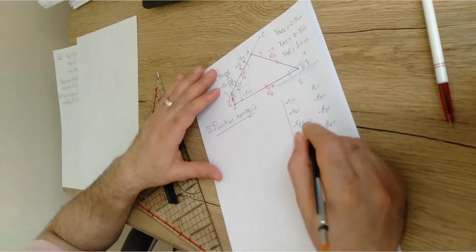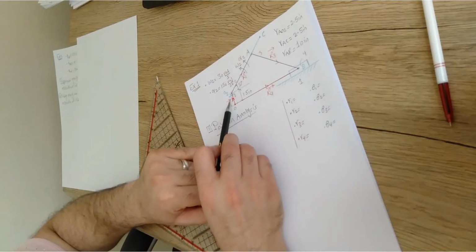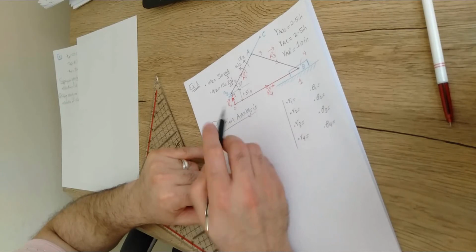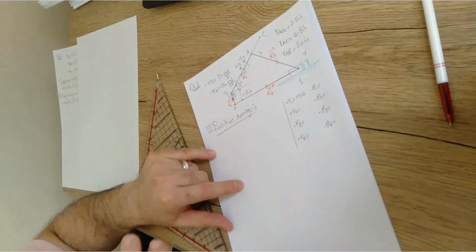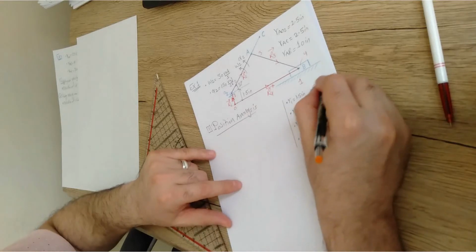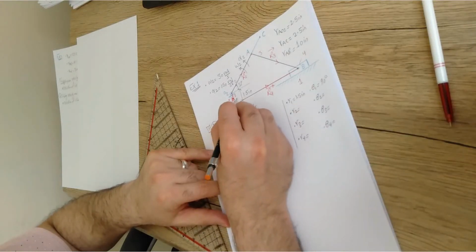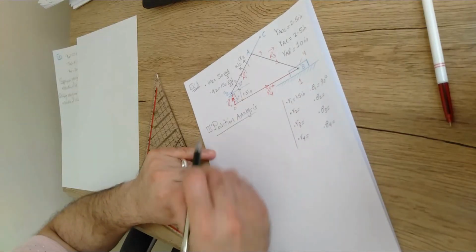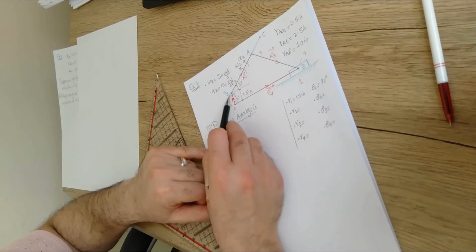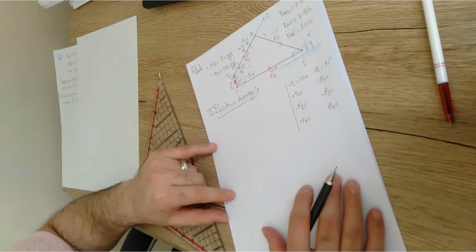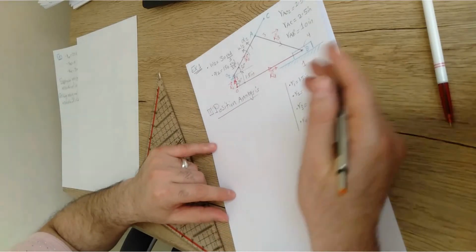Make sense? So R1 should be the distance between O and O2, which is already given as 1.5 inches. Remember that we are limited to just 2 unknowns. Theta 1 should be 90 degrees, right? This angle is already given as 90 degrees. Why? Because you define this angle from the start point: draw a line to the right, rotate counterclockwise till you hit the R. This gives us R1 or theta 1.